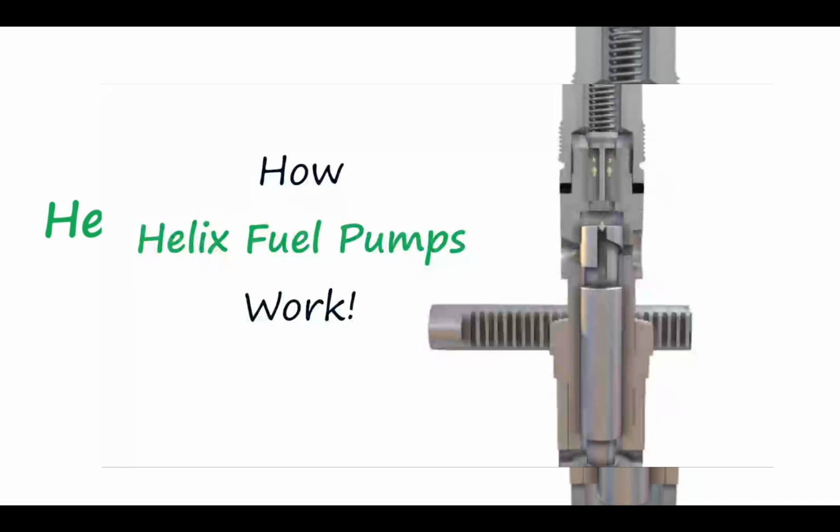So any fluid, if it has two passages, one with very high resistance and one with very low resistance, where does it go? Through the lower resistance. And the lower resistance is to go back again to the pump's casing at a 5 bar pressure rather than being injected at 1000 or 2000 bars into the injector.